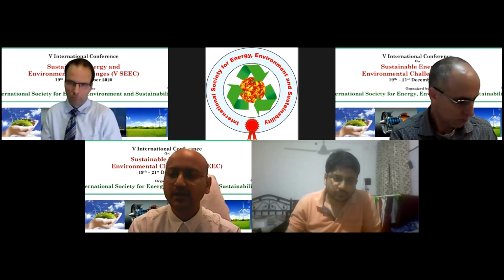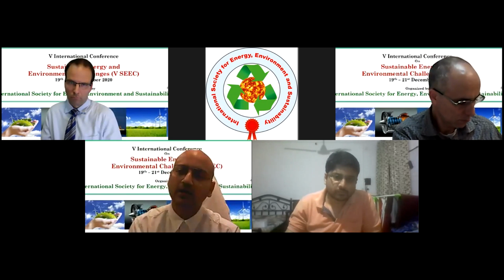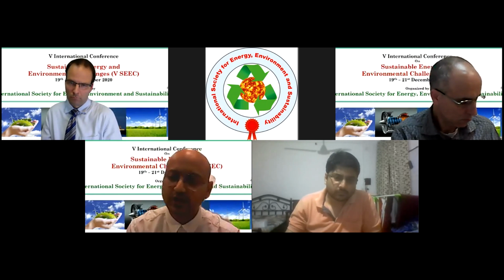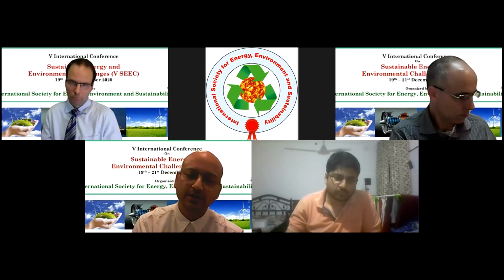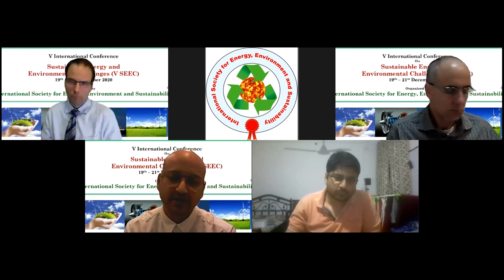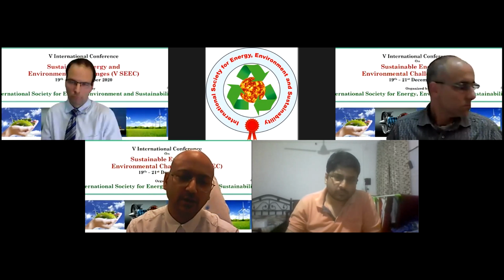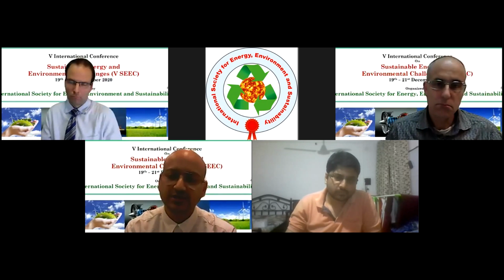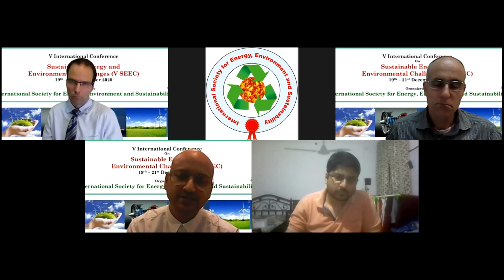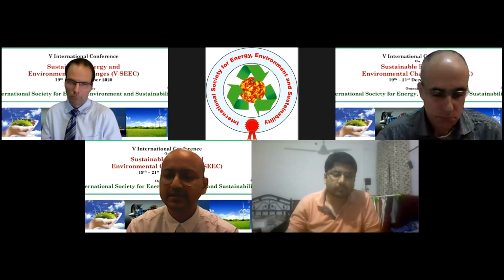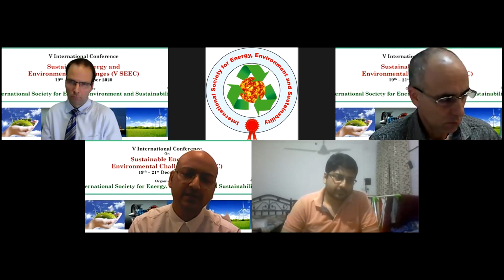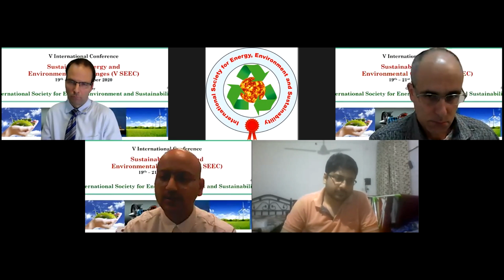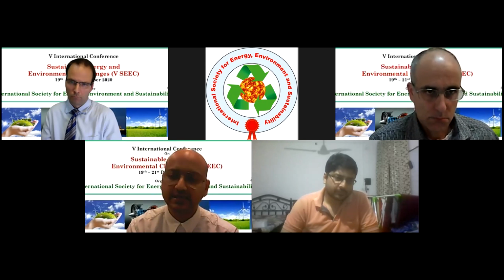So it depends. Generally, in most conditions, if the water quality is good, RO is not a good option. Alternatives like nanofiltration and ultrafiltration can be adopted. With this, I would like to invite Professor Kasher to talk about this: is it feasible, or is it a good idea, to have these RO systems at home or not? So I think I have given some background, which Sachin, I think, is asking for.